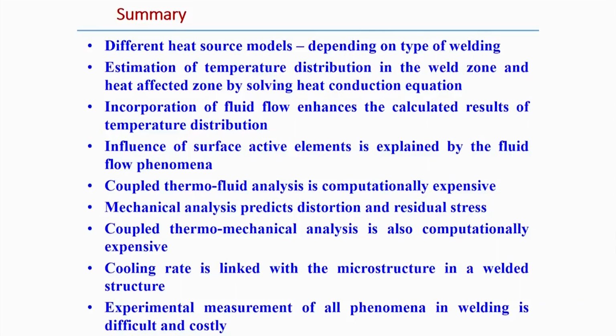And then the cooling rate: from this numerical model, if we know the temperature distribution, we can estimate the cooling rate, and that cooling rate can be linked with the microstructure in a welded structure. So, by simply calculating the cooling rate, it is possible to predict the microstructure present in the welded joint.